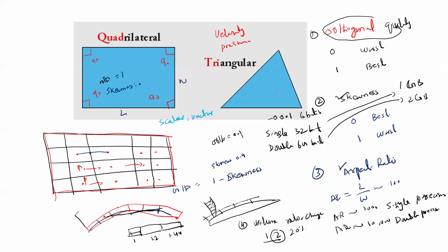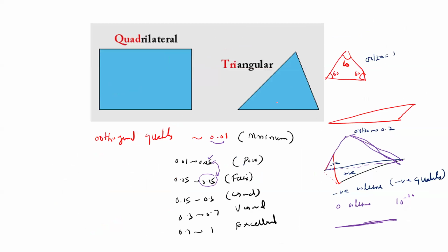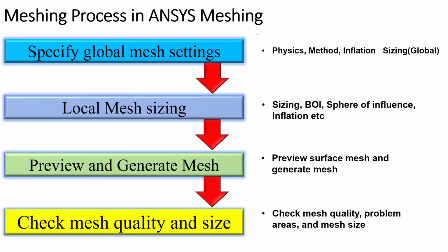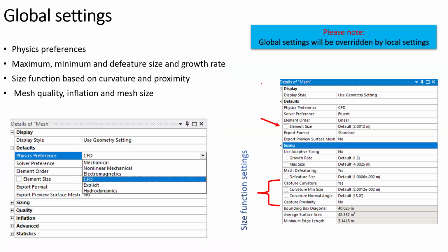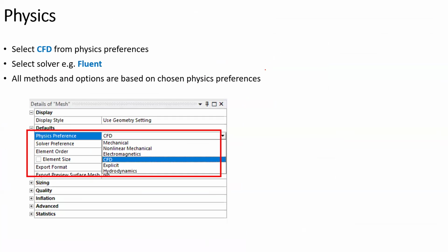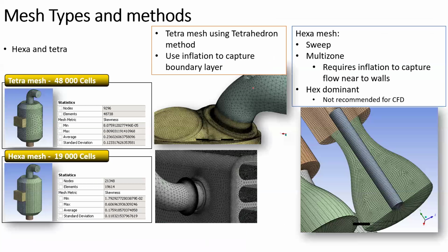And we discussed the mesh quality and what should be the minimum quality we can accept for CFD. We have also gone through the different mesh metrics and their qualities, and whether their ranges are okay for CFD or not. So we have gone through all of these things. Then this is a general process, that is, what should be the procedure for defining the meshing in any CFD software. So then we have gone through all of these details. We discussed them in very much detail actually.